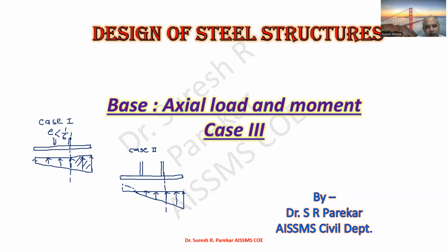In case 1 we have some value P minimum, and we have compression throughout. In case 2 we have zero value over here, and this value x is less than the length of the base plate. In case 3, a considerable portion is under tension, and therefore we have to consider both tension as well as compression.